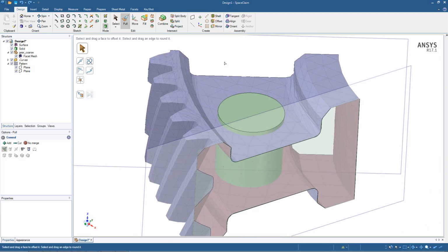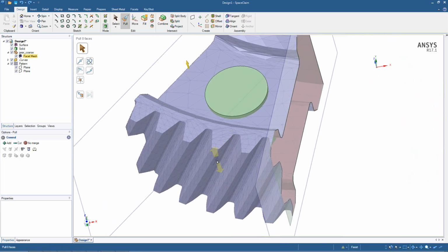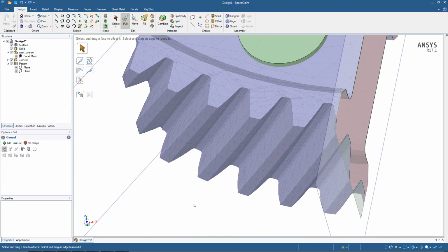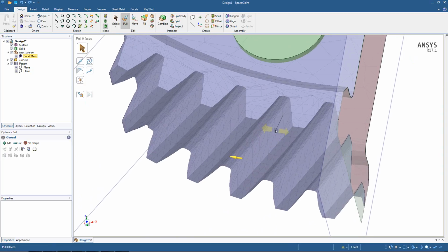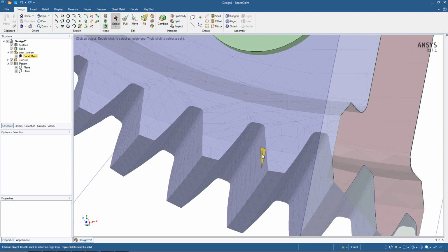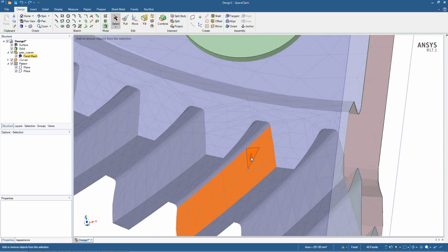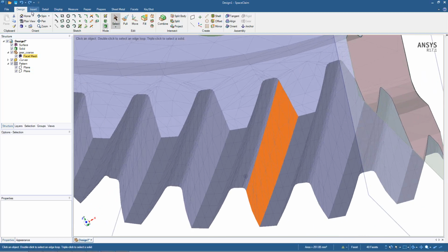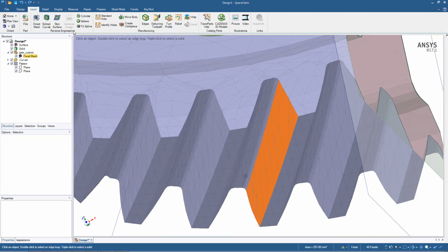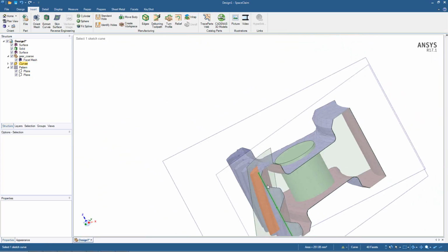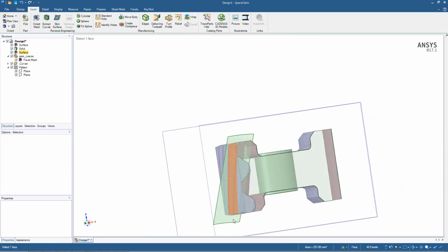The last thing that we're going to want to do is create a solid that represents this gear tooth cutter profile. So we can create surfaces that go through this profile. And we can do that by, again, simply just double clicking on these facets and then getting all the facets that make up that one profile through there. And then in the reverse engineering section, there is a Fit Spline option, which will fit a spline surface through all of these facets. And you can see it just kind of arbitrarily extends beyond the facets that we've selected.